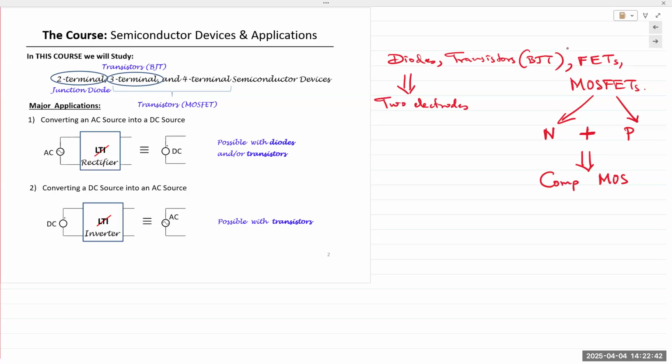So it was good to have a diode. They could build circuits with it, but they also wanted to control the flow of current. So they inserted a third electrode, on the side. You'd apply a potential to the third electrode, and it would control the flow of electrons, and you could manipulate the flow of electrons going from cathode to the anode.